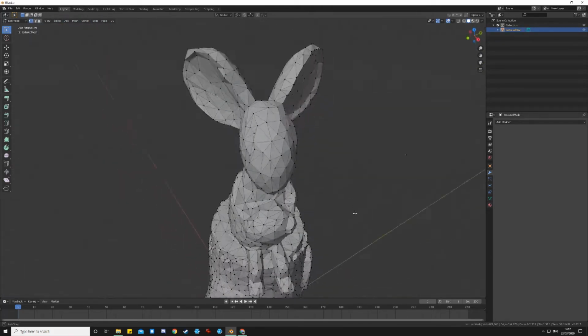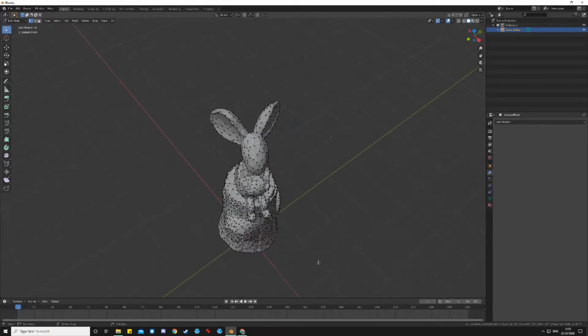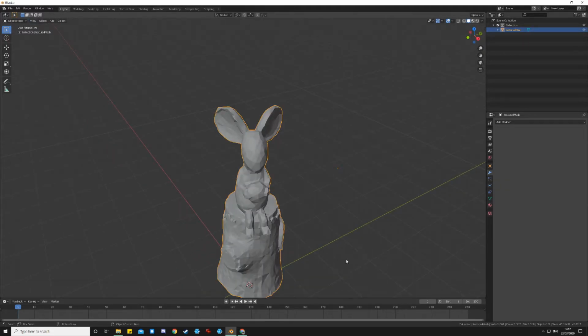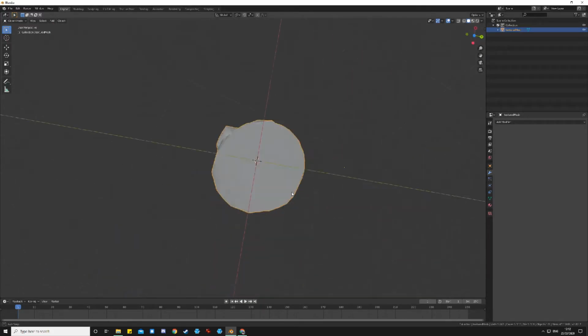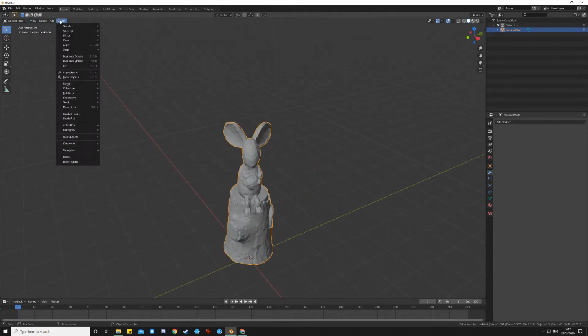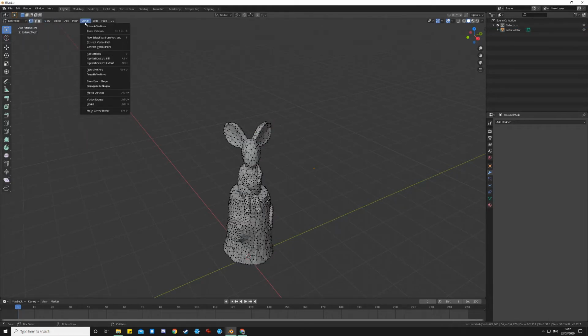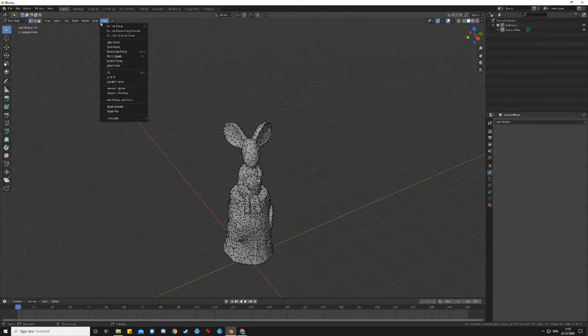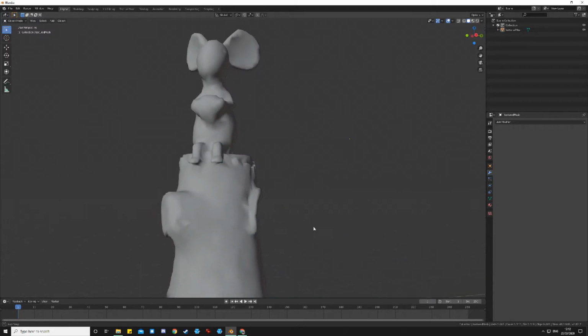What's the next step? There's no holes in it, which is brilliant. So we've done the filling, and now we need to do some smoothing. So go back to object mode, and we'll get to see the kind of blocky version of it there. But what I'm going to do, is it in edit mode I need to do it? It is in edit mode. You go to faces, select all, and then you go to shade smooth. So now that's made a nice smoother version of all those objects.